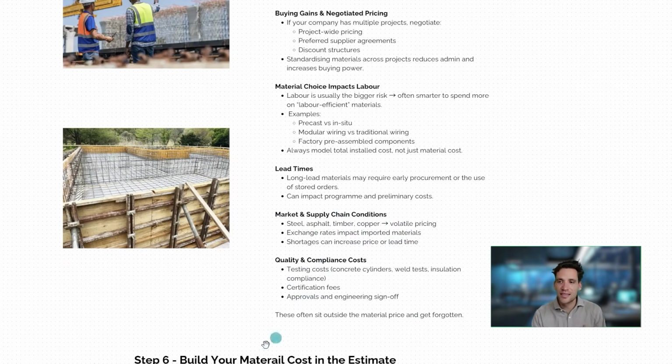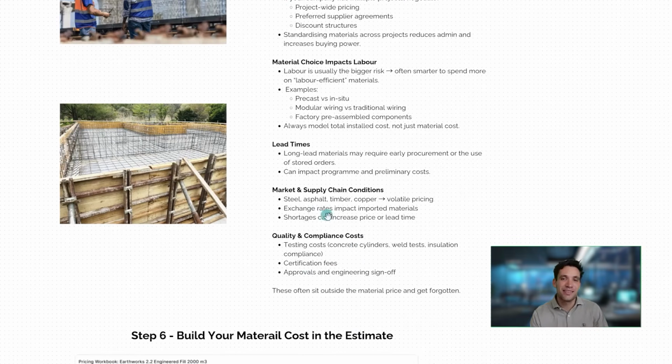And finally, this is just something to think about as well. You'll often have to get test certificates and compliance checks for the materials. Just need to check, is that something your supplier is going to cover and do? And are the test methods appropriate for what you have to provide to your client? Or are you doing independent checks? In which case, where is that cost covered?